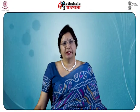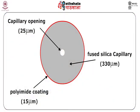So, in capillary gas chromatography, there are capillary columns which are thin fused silica, that is purified silicate glass as capillary, which is used as a stationary phase coated on the inner surface. Capillary columns provide much higher separation efficiency than the packed columns, but are more easily overloaded by too much sample. For petroleum product analysis, we have to again maintain some specific conditions as we have done for the gas chromatography, and that we can see here.